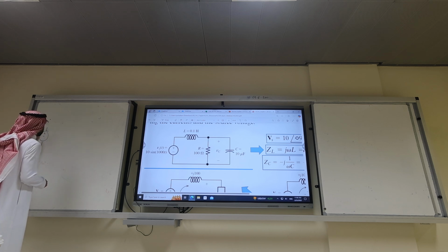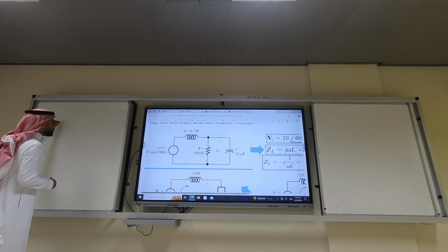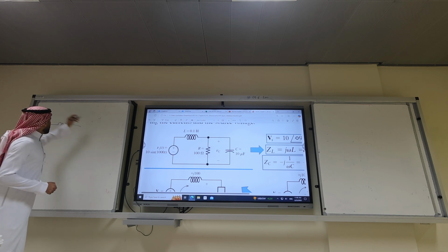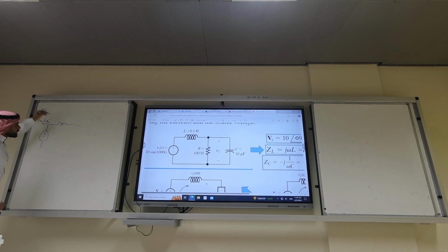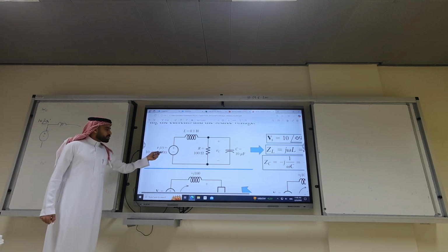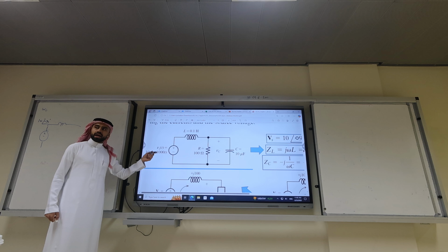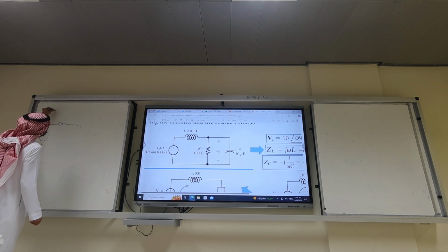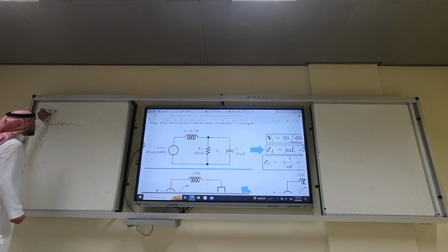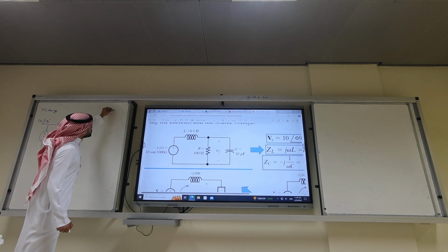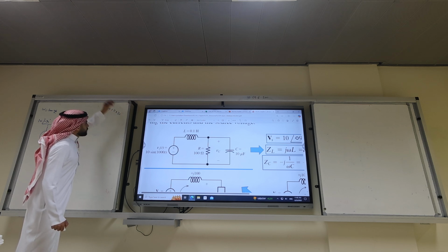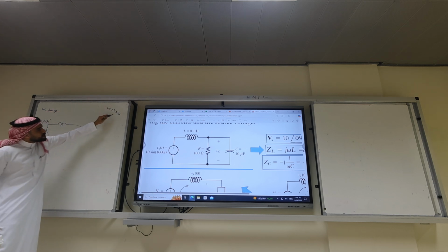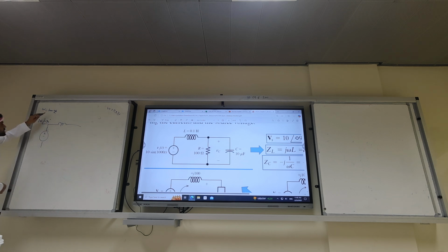We're professionals, right? So we put the inductor. Okay, what is omega? Always write omega in the corner. What is omega? It is whatever is before the t. Omega is 1000. What's the unit? Radians per second. Sometimes omega comes as something like 2 pi 20. Sometimes they write it that way, but in some examples to make the numbers easy, it's written as a number. Get it? Don't get confused.